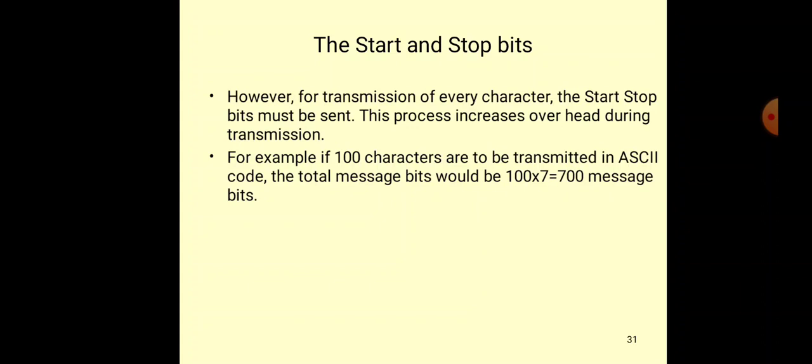Generally in asynchronous transmission, we send one character with start and stop bits. In an asynchronous system, the transmitter and receiver clocks are free running and set to approximately the same speed, but not exactly the same. The purpose of start and stop bits in the asynchronous system is to identify the beginning and ending of the character by the receiver. A start bit is transmitted at the beginning of each frame, and at least one stop bit is sent at the end of the character. The stop bit leaves the line or channel at binary 1, and the start bit is always represented by 0.